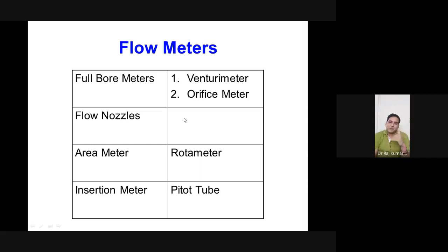Your 39% has gone away. So you derived based on Bernoulli taking ideality, but it's not ideal, as we also know. It is the sudden contraction which gave the losses, and to incorporate the losses the discharge coefficient in an orifice is 0.61. Therefore, it's not preferred.